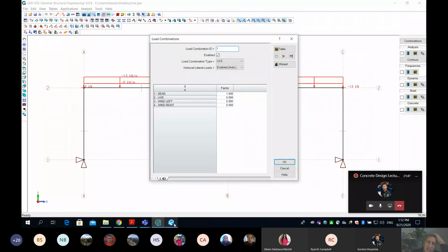As you guys remember from maybe a week ago or 2 weeks ago, I said when we design a structure, we're not only focusing on failure, we also focus on the performance of the structure on a daily basis, which means deflection, vibration, cracking. Anyway, guys, if you drop this menu, you're allowed to change the type of the combination from ULS to SLS and the opposite. Okay. Now, let me show you how to create the next one.